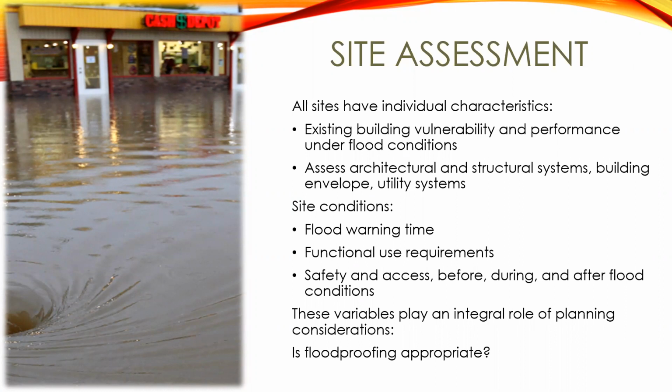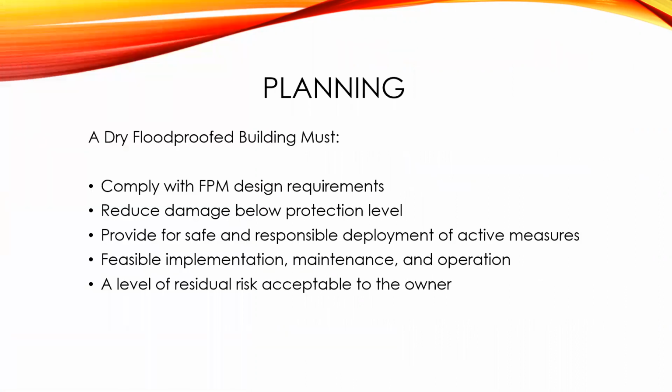The same goes for the utilities: the mechanical, plumbing, gas systems, and electrical should be elevated. We can also floodproof those and put them in their own enclosure with flood walls around it, or they could be designed to be submerged, whatever the case may be. We have to consider those as well. And then there are two required plans, for emergency operations and for maintenance and inspection. None of that information was in the older technical bulletin, so they've really amped it up, probably because of the rate of failure on dry floodproofing.